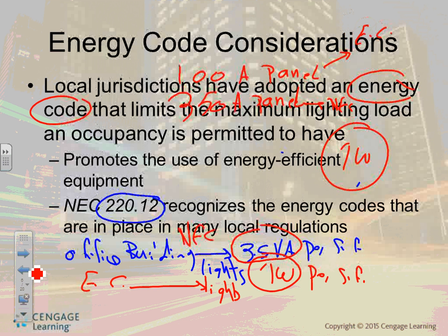That was changed in 2014, where they allow you, if you have a lighting control panel that you can control and monitor your lights, no problem, and you are installing it, which is not hard to do, then to meet the energy code you can say, well, here's the NEC code book. Remember that fancy stuff I told you guys about lighting panels, and you came up with 350? Well, let's do the energy code, 1 volt amp per square foot, and see what you come up with. We typically come up with almost 1/3 of what the NEC code book gives, and you size your cables and conductors based on that.